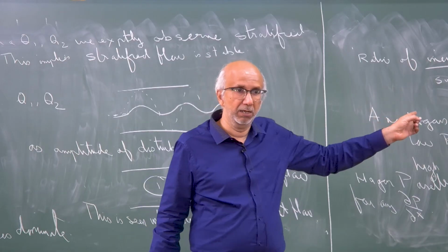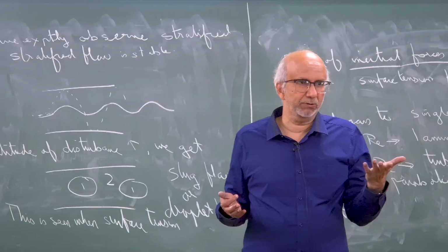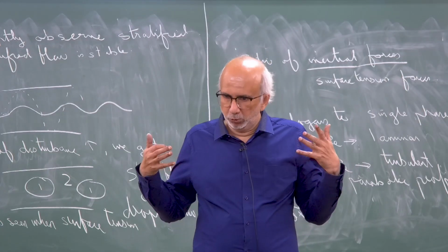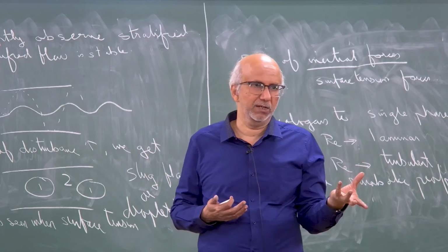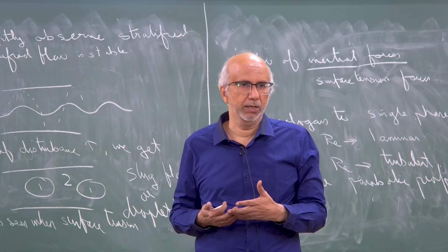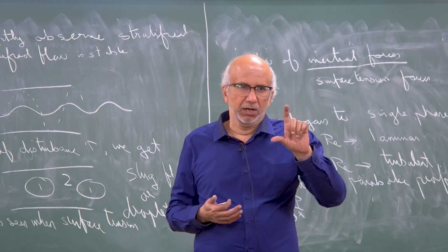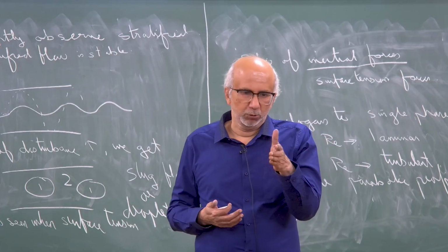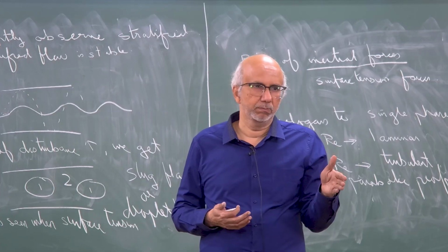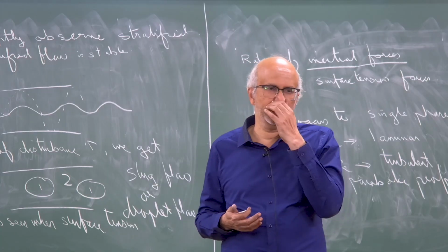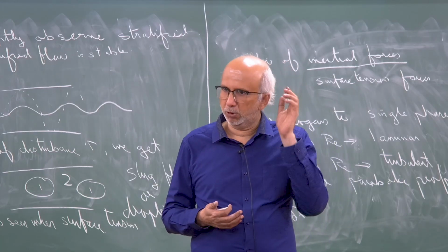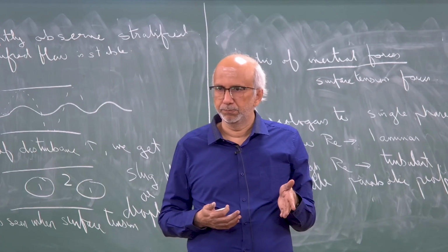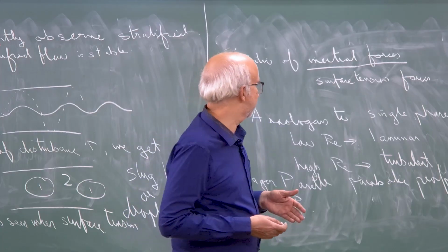Same thing with laminar. In the stratified flow, you found the stratified flow solution. What I am saying is you may not always get it because it's unstable, and that is the reason when you do two-phase experiments, sometimes you get slug flow, sometimes you get stratified flow, okay. And how do you find out this transition from one flow to the other? You have to find the point where things become unstable, okay. So, I just wanted you to be very clear about this thing. Just because you have found a solution does not mean experimentally you will get that solution, okay. So, that is the point, okay.